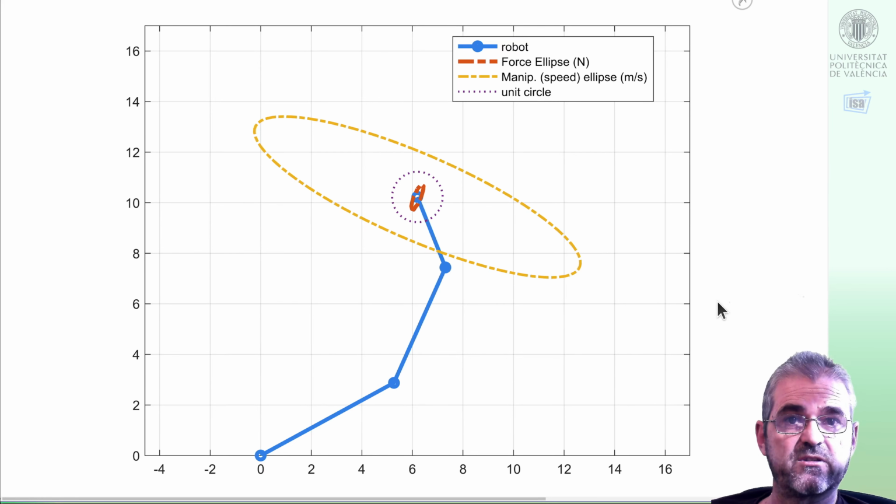So somehow they are two perpendicular directions that behave like a one degree of freedom mechanism. In my pinion gear, if I multiply angular speed by 10 to get linear speed, then I divide torque by 10 to get linear force. Then this multiply, divide. In general, the singular value decomposition sort of decouples a generic Jacobian into two perpendicular gears.